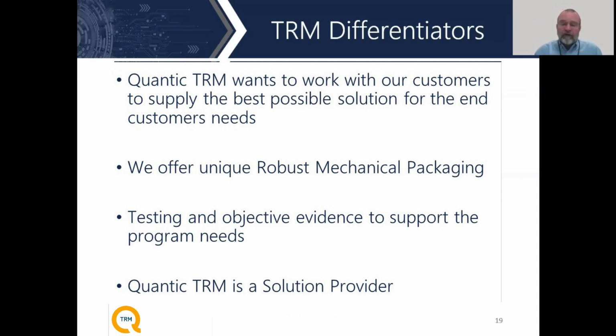Again, packaging is a big part of it. We have to make sure that the parts can survive the environments that they're looking for, and where the connectors are located, especially with a lot of these beamformers that are interfacing directly to the antenna aperture. You'd be surprised at how often we get requests for connector spacing, which may seem very odd to most people. But if you look at the entire system, they set up the connector spacing, for example, to match the element spacing. Therefore, they can have a direct blind mate connection from the beamformer directly up to the aperture, which makes a lot of sense from a system standpoint, although we do end up with some very odd connector spacing by doing that.